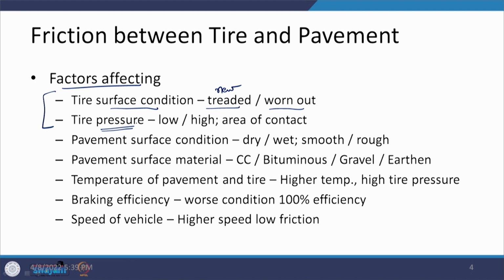Now, when you are talking about tire pressure and the air is less, then in that case the area of contact of the tire with the pavement is going to increase. But if the tire pressure is more, then the amount of area in contact with the pavement is relatively lesser. When this happens, we are not talking here in terms of a load distribution, but in terms of the contact area which is going to generate the friction. And again, this becomes one such factor which needs to be taken into consideration.